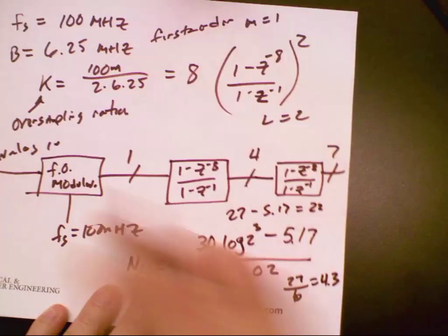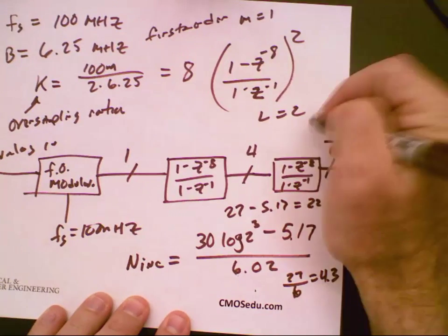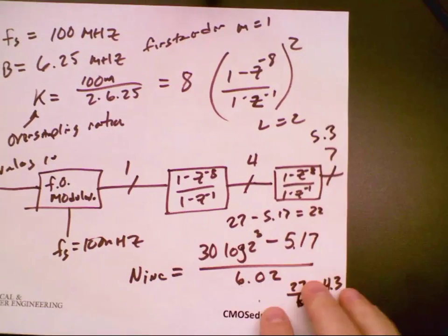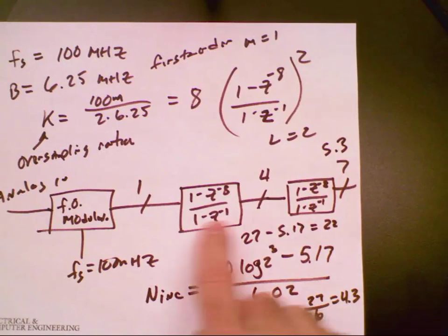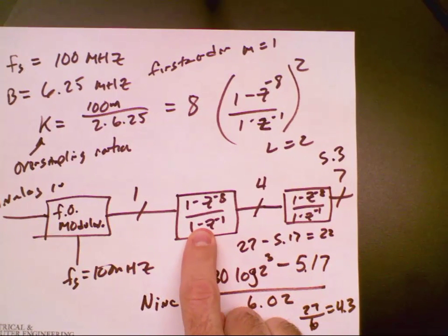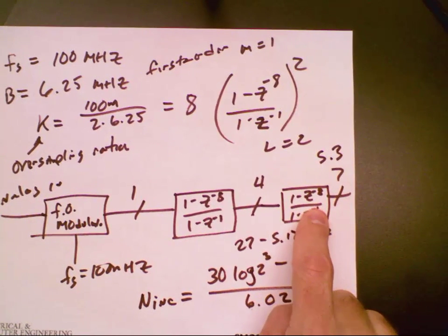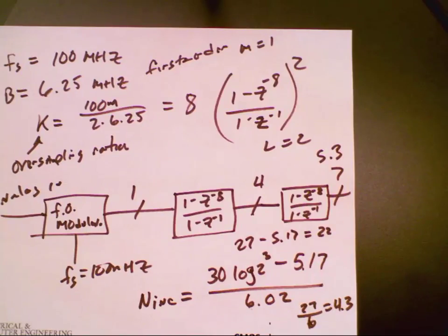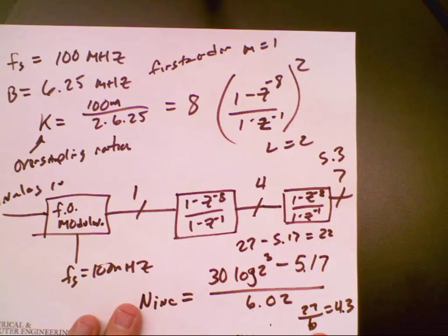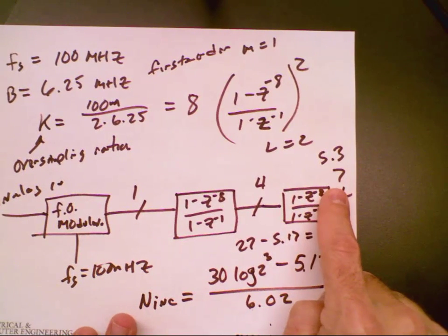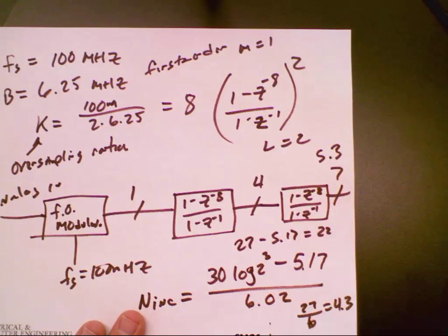So I had 1 bit coming in. Now I have 5.3 effective. Is that correct? Could I have gotten away with 1 filter? Nope. So that's why I have the 2 filters. So I have 7, that's more. Now the lower bits are not going to be that significant. They're going to be a little bit noisy because I'm only getting an effective increase of 4 bits and I'm getting an output of 7, but that's fine. Any questions?